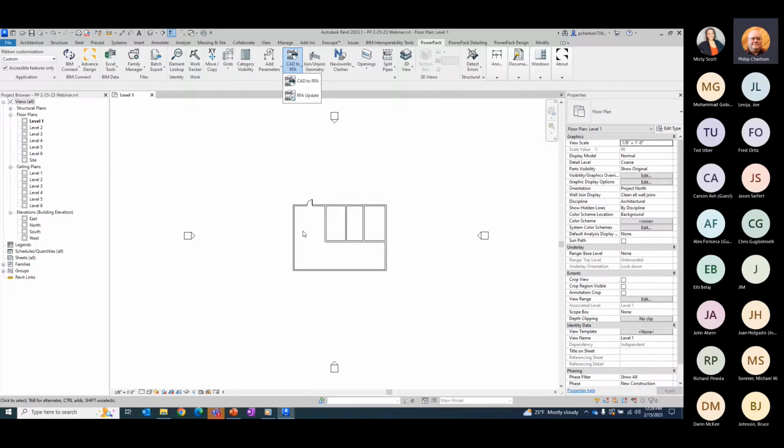Now it's not going to fill in all of your parameters, but it's going to add the parameters so that you are able to put that information in. So hopefully if you are bringing in any manufacturing data, you're probably still on that manufacturing website. So hopefully they have some kind of spec sheets that you can grab and then plug into those parameters when you create that family.